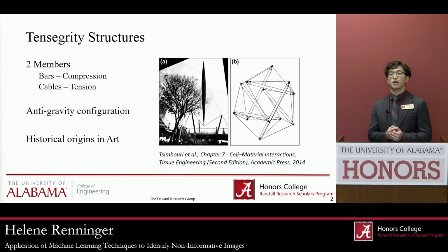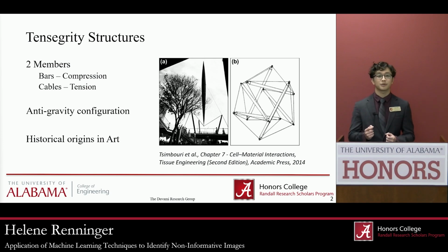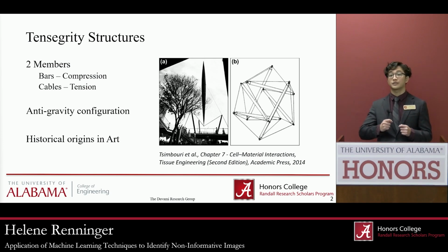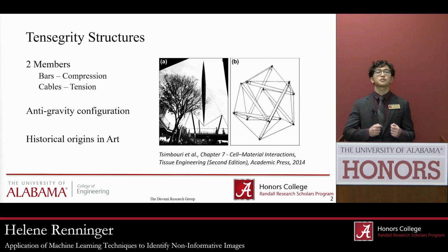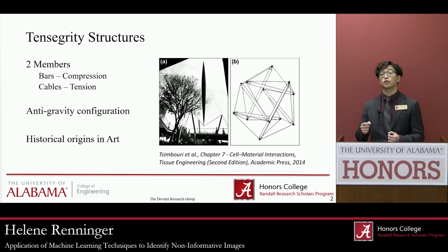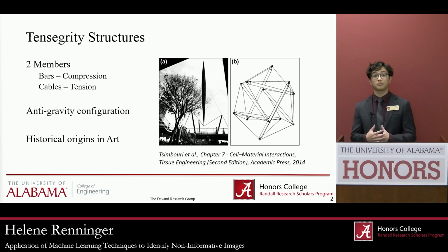Well, they can best be described as a network of compressive members held in tension by a network of tensile members known as cables. So this combination of bars and cables allows for a self-stressed equilibrium state that resists external loading, including gravity. This is where we come with the anti-gravity configuration of these elements, presenting unique properties as mechanical